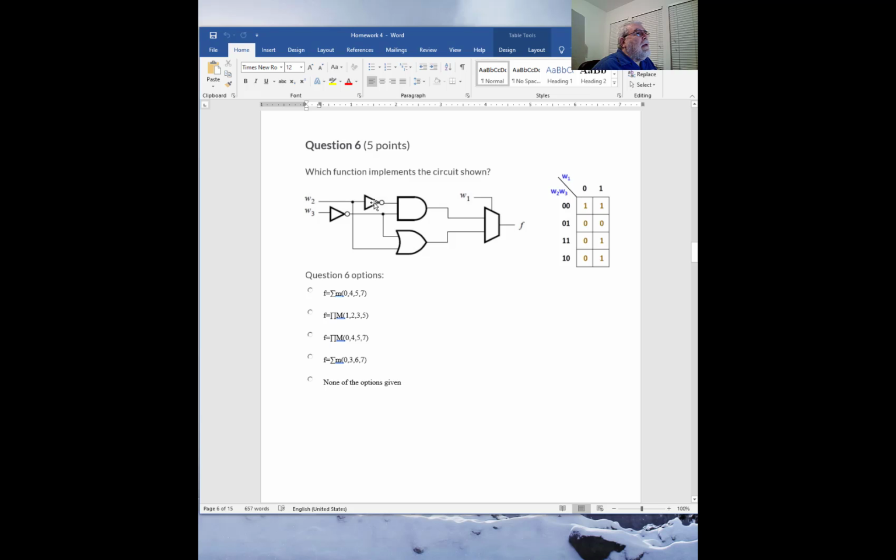It's clear to see that this branch here, because it's an AND, is going to be 0 with the exception of when this is a 1 and this is a 1, and that would be W2 0 and W3 0. So both zeros is the only chance in which this is going to be 1 for the upper side, and this is the case. The rest is not.